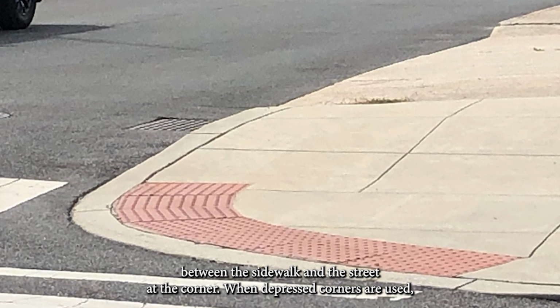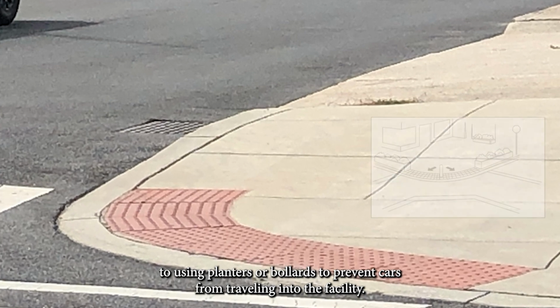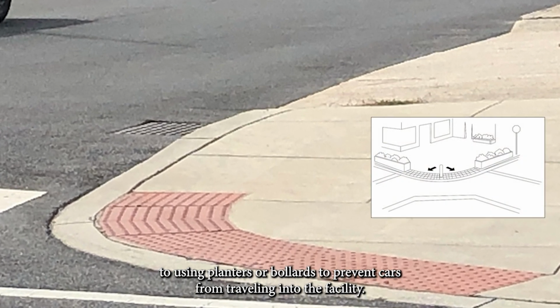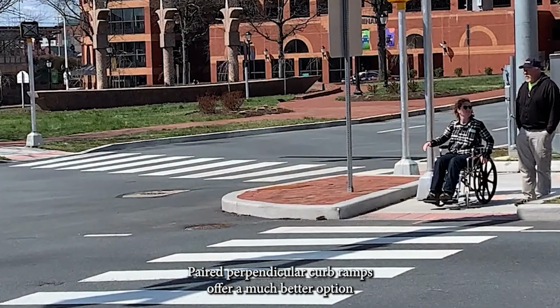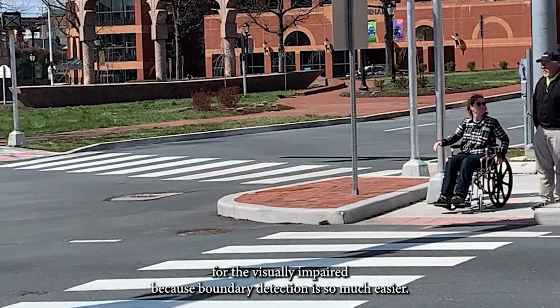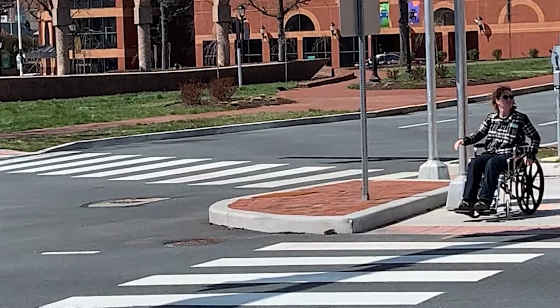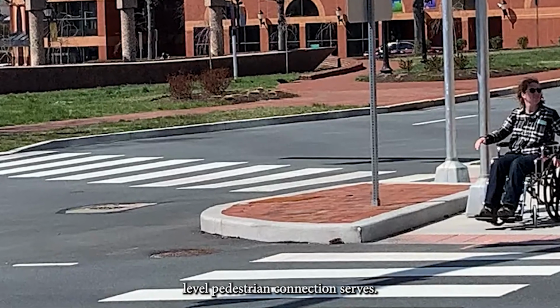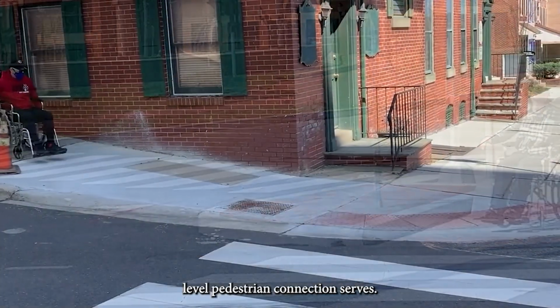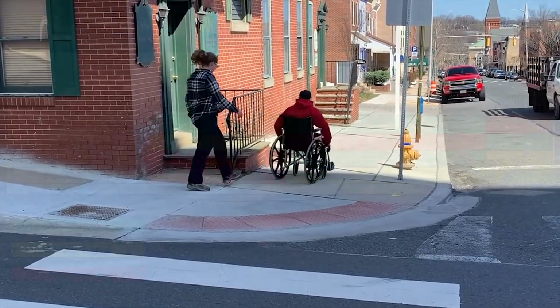When depressed corners are used, consideration should be given to using planters or bollards to prevent cars from traveling into the facility. Paired perpendicular curb ramps offer a much better option for the visually impaired because boundary detection is so much easier. The slope on any required turning space is controlled by the roadway that the street-level pedestrian connection serves. This may lead to challenges for users who are not using the crosswalk.